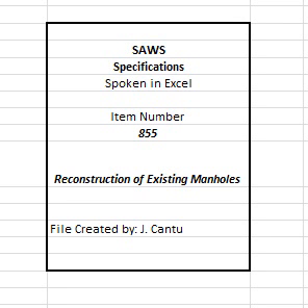C478-12A. 4. Mortar. Mortar shall be composed of 1 part Portland cement, 2 parts sand, and sufficient water to produce a workable mixture. When used to plaster manholes, it may be composed of 1 part cement to 3 parts sand. Lime up to 10% may be used.